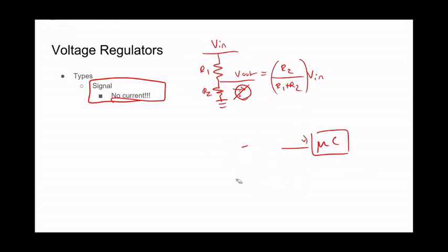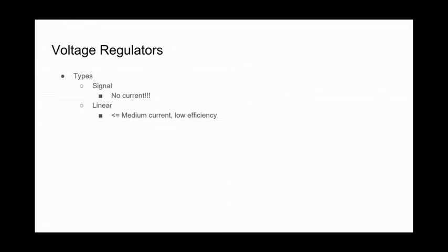So you cannot use this to power anything. If you do, two bad things will happen. First, the equation will break, which means your math is wrong. The second, and probably more important, is you are dumping immense amounts of power over these resistors, which will, in essence, turn into heaters and catch on fire. So please, voltage dividers are great, but only for dividing signal level voltage or regulating a voltage at the signal level. Next, let's talk about linear voltage regulators.